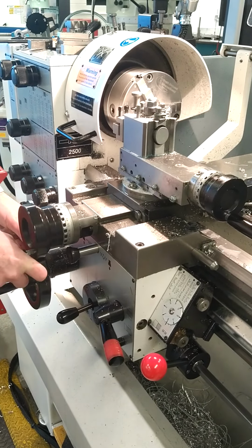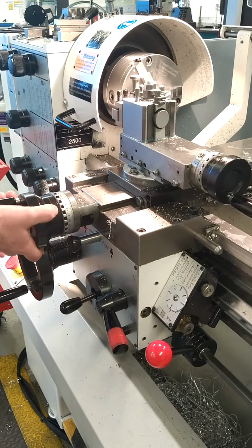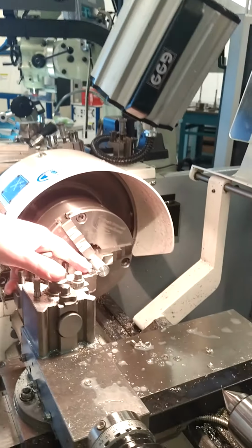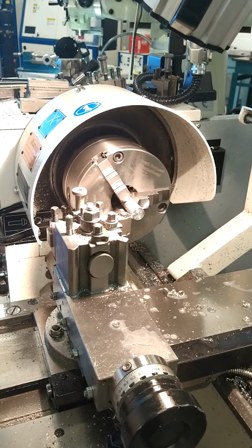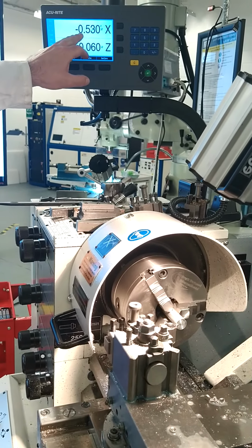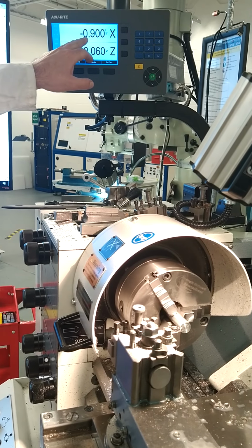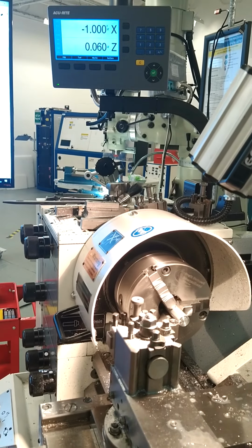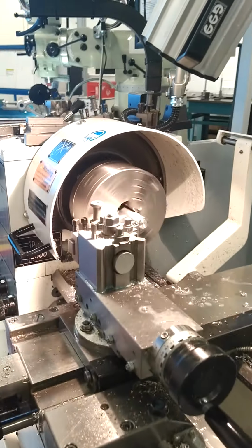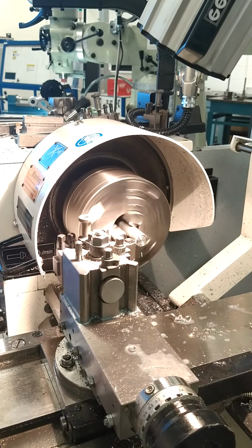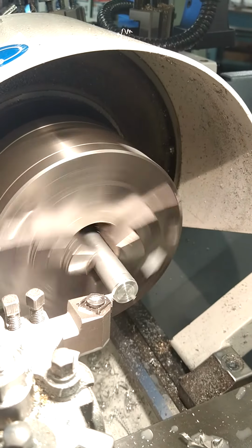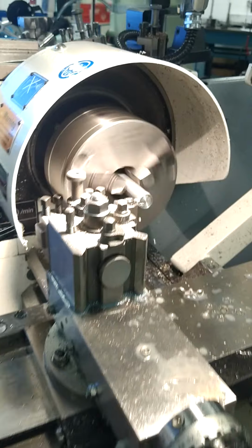So now if you want to turn down the diameter, we have our X set. X is put to 0, X 0.2 is touching the work, and you want to reduce down the diameter by 1 millimeter. We adjust in 1 millimeter. Power on your machine, and you're traveling down in the Z-axis now, reducing the diameter of the work. You want to avoid doing this fast movement.